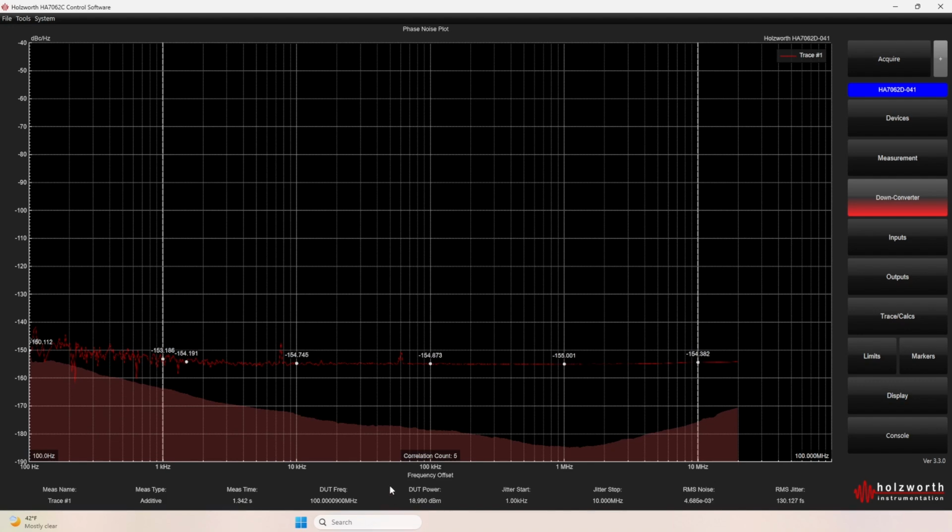So that's pretty much how to make an additive measurement. If you run into a couple issues with the software, say channel 1 or channel 2 aren't connecting right away, it's always good to double check connections, but it may also require you to increase the power output of the signal generator itself in order to get the LOs enough power, because you are splitting the power down.